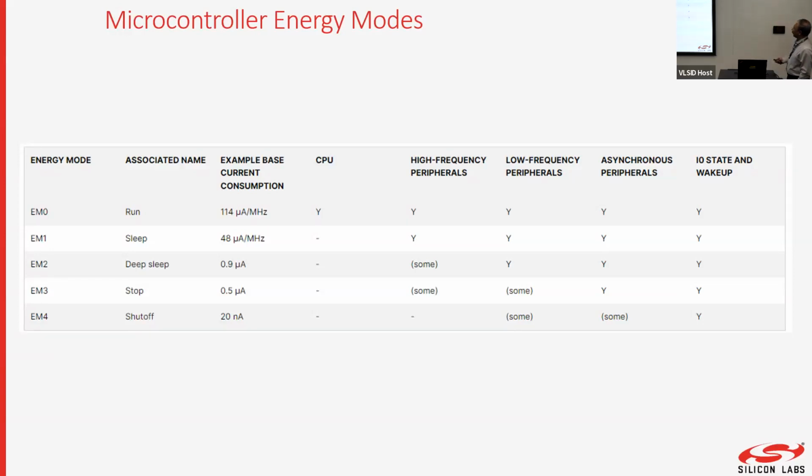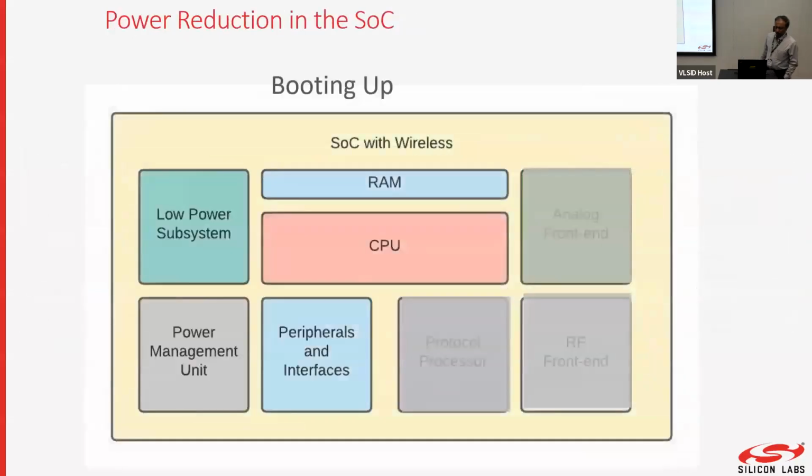A wake up circuit, you can have many different ways of waking up. You can have a timer based wake up. You can have some other external counter based wake up. For example, you can have an external counter which gives you an interrupt. So microcontrollers have different mechanisms.